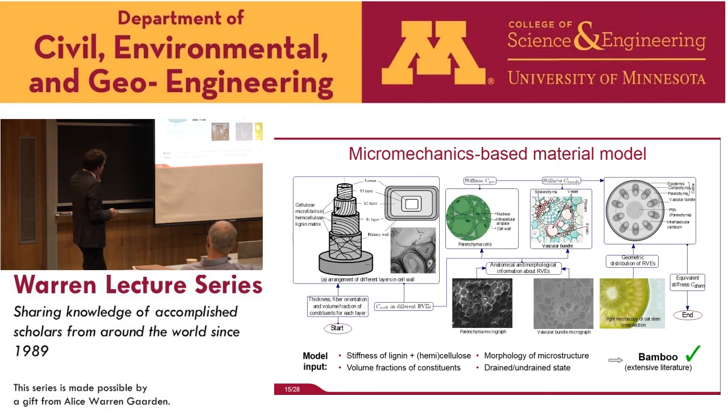Usually, if you want to do that in as realistic a way as possible, you would have to go away from analytical approaches to computational approaches. Yes, we would do computational homogenization. But since our analytical model works so nicely, we would like to keep that one and also try to upscale strength parameters. What we want to upscale is plastic strain. For that, our idea is to decompose that from elastic strains and treat it as a separate variable, and then include plastic strains at a certain level and upscale that with the same type of analytical technology we have for the elastic part. That would be our first idea, and we're working on that right now.